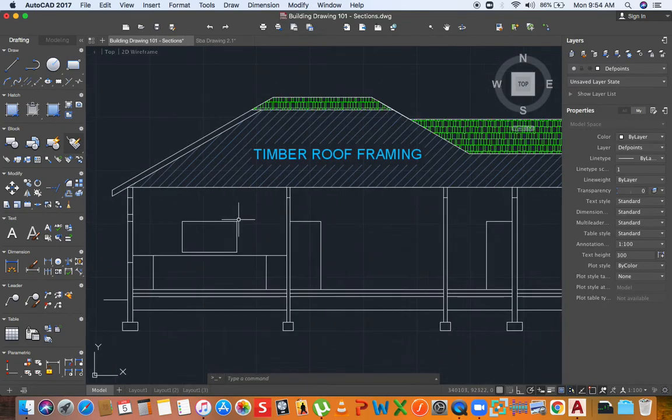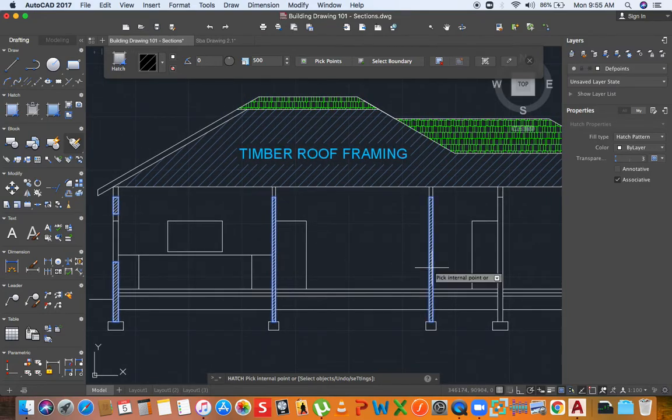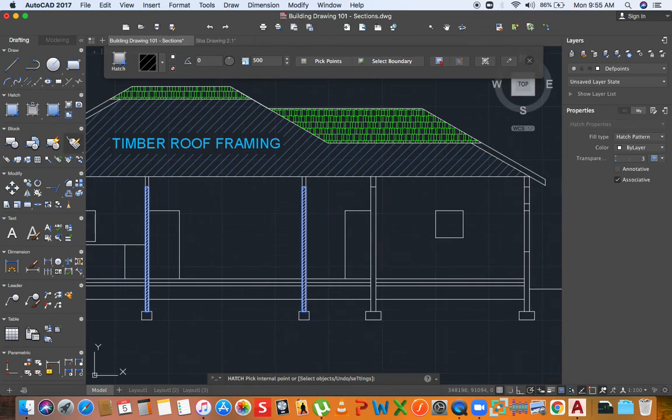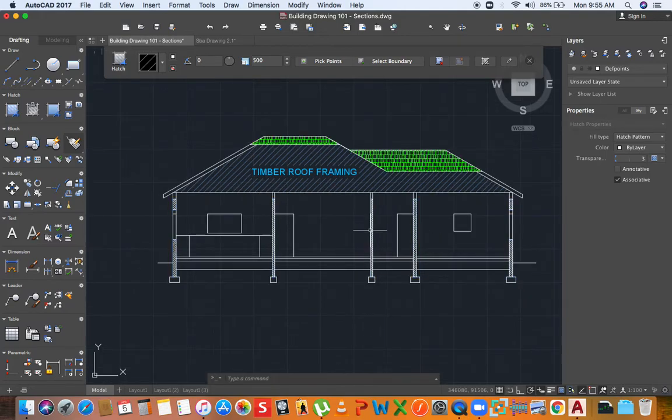We're going to do some hatching. I'm going to select my hatch line. I have to select a reasonable scale, 500 rather. Select the scale before you actually click here. You have less troubles when you're doing that. And everywhere that a wall, the block wall, like concrete blocks will be used, you put this. I think that's it for that.